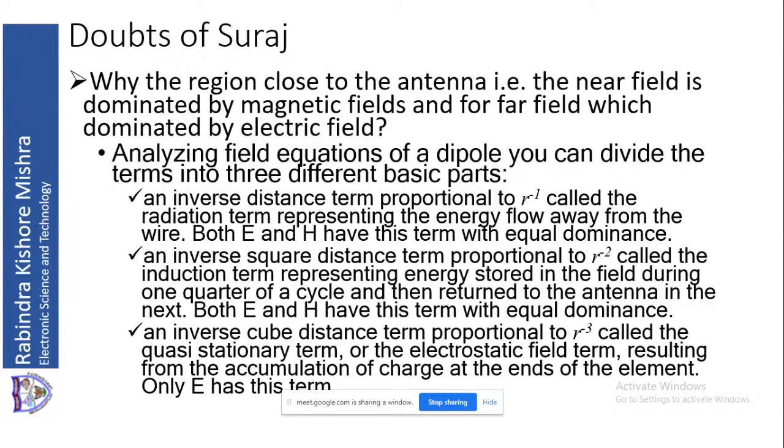So that is a small deduction that you must have seen in +2 when you have read electricity, static electric. So there you must have read this. So that means you require two charges, right? Now, when we are considering antenna, it is oscillation of two charges, two opposite charges separated by a small distance. Hertzian dipole is that. Since it's oscillation, we assume that at both the ends of this separating distance there is charge accumulation, which is positive in one half cycle, negative in the other half cycle.